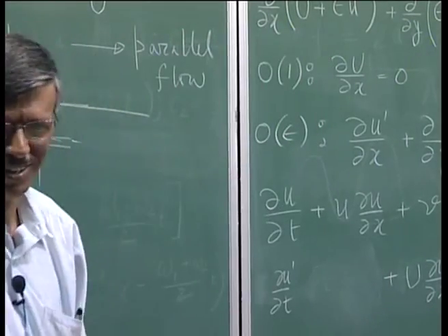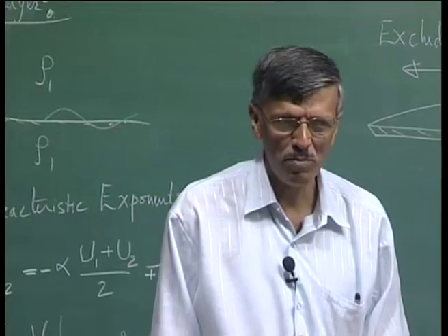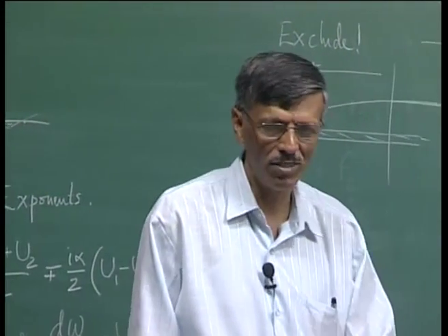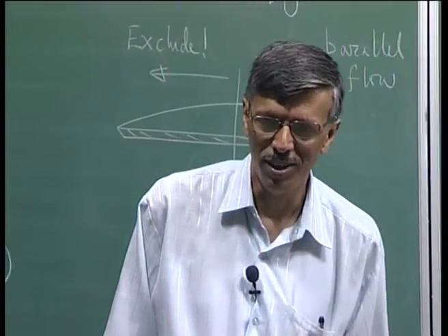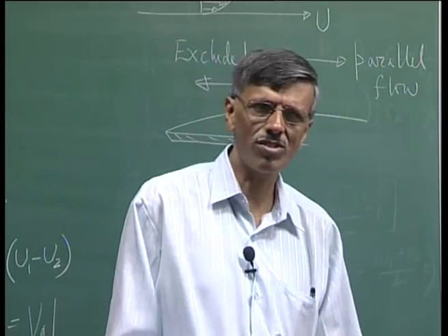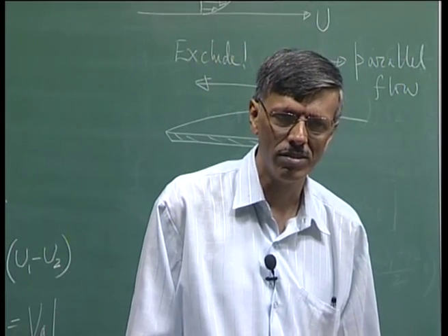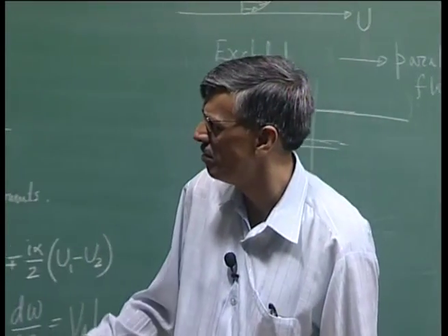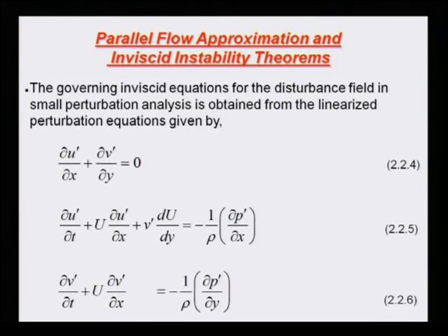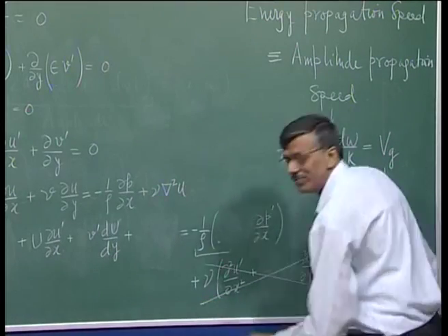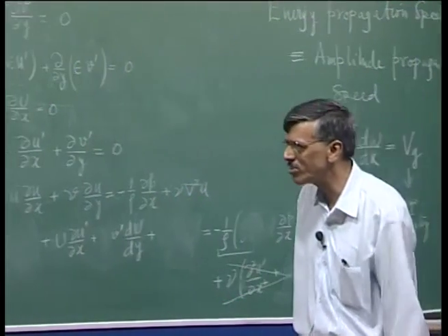Of course, this is a similar approach here, because we cannot handle the full thing, and then as an afterthought we say viscous action is there, it has to attenuate. So let us try to find out the more critical case by dropping the viscous term altogether. That is the essence of inviscid instability. So inviscid instability would mean that we do not need to look at this term. And that is what you are seeing here.